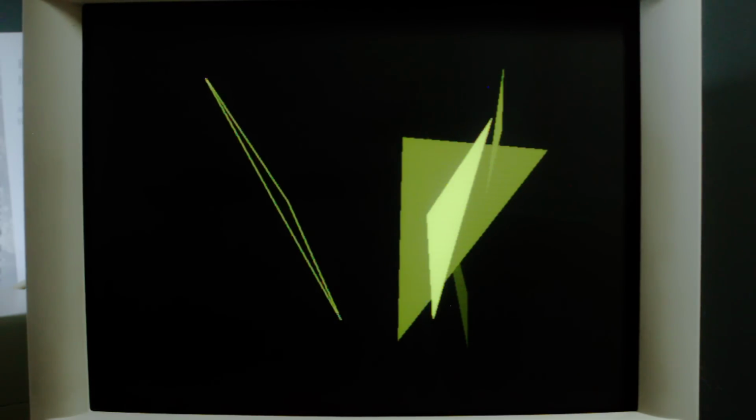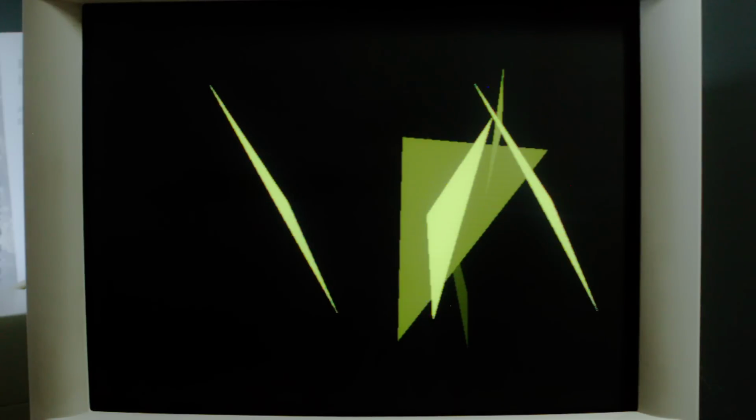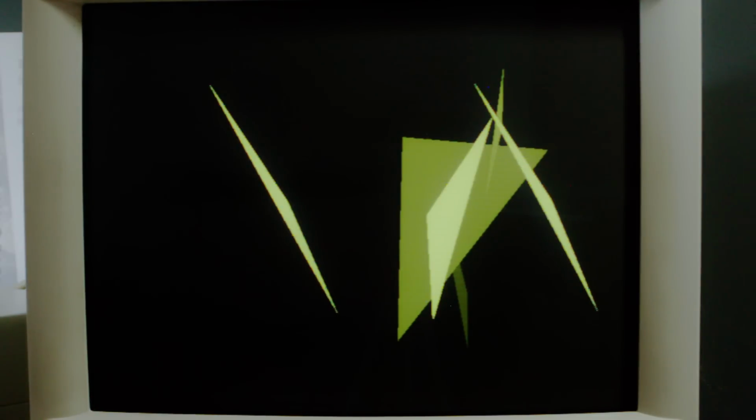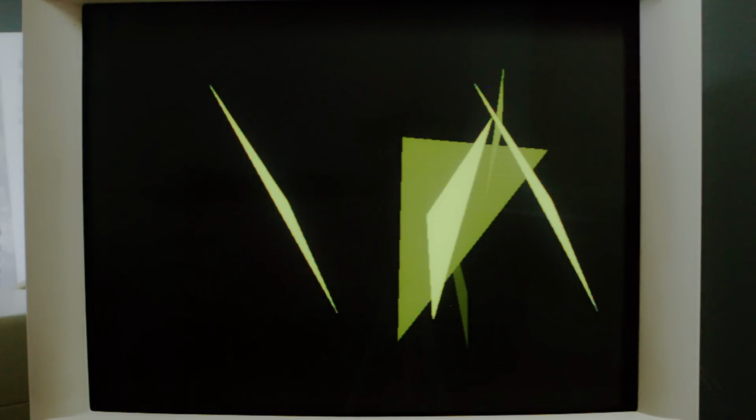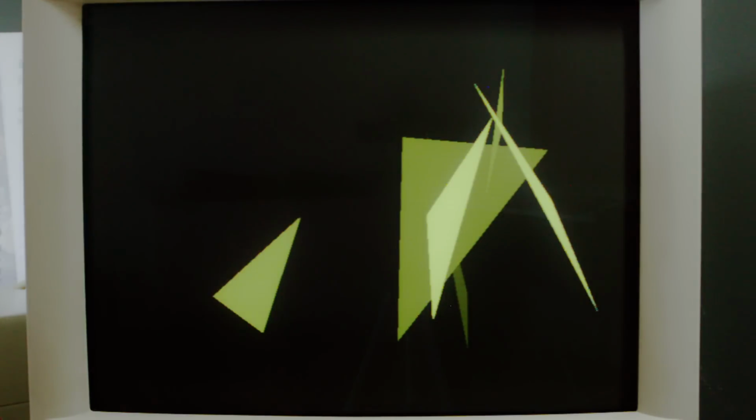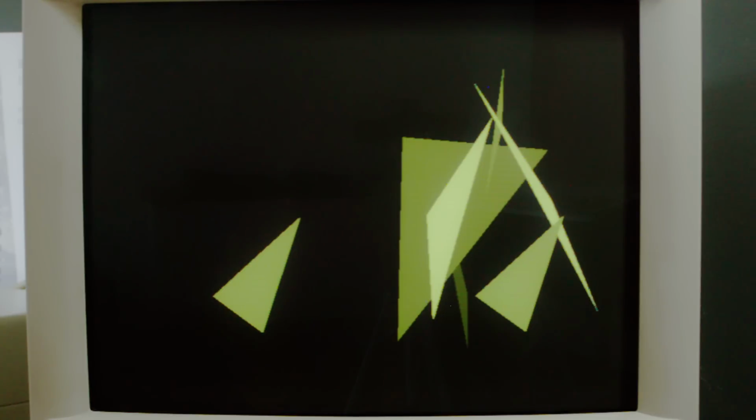So when that bit 7 gets set, 2 to the power of 7 is 128, it effectively adds 128 to the color value. And so what was happening is it was basically just doing a whole load of black pixels because I just had black in my color palette. So the solution was pretty easy. All I had to do was duplicate the lower half of the palette in the upper half and basically make sure there's a full 128 colors there.